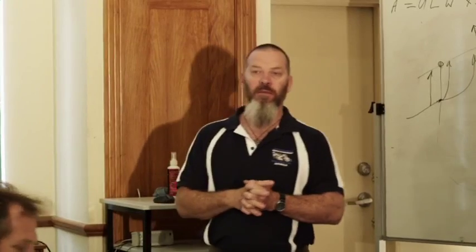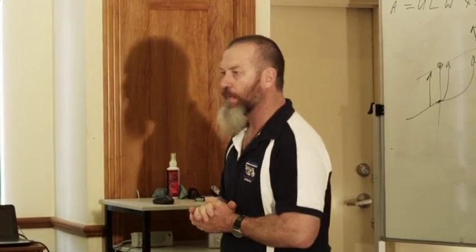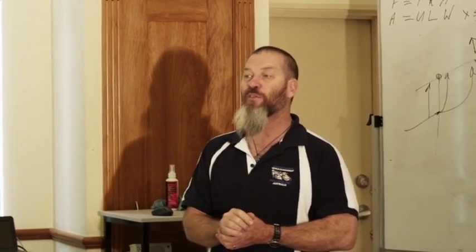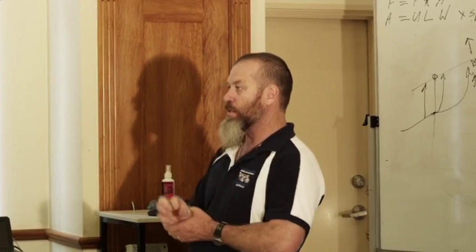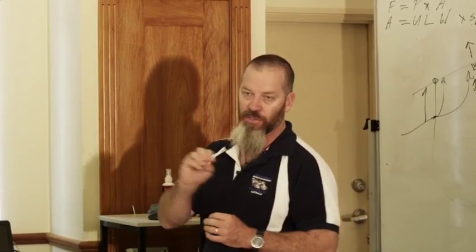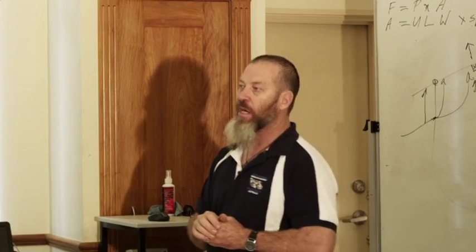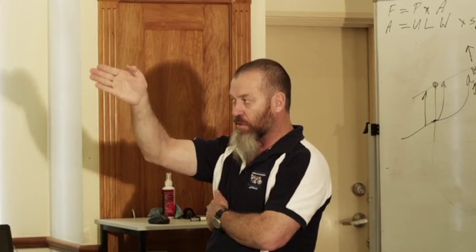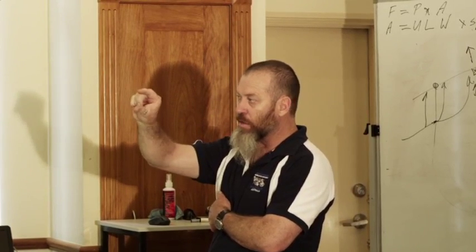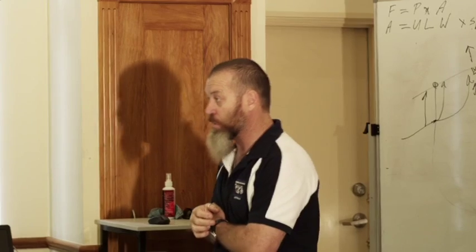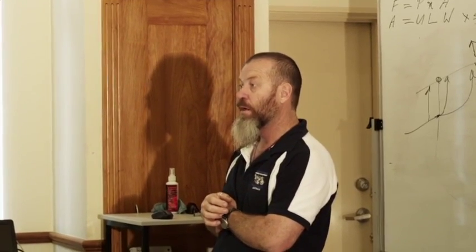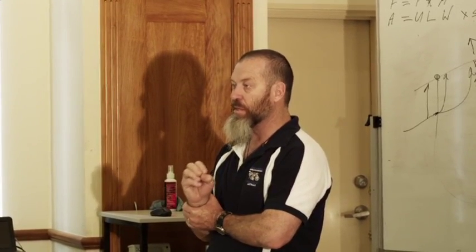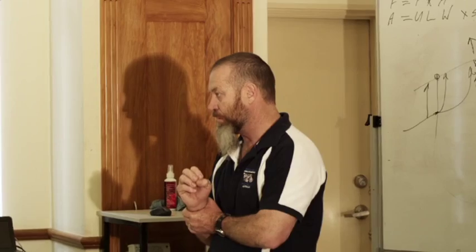Now, when you get to your span tables, and these are my rules for Task 57, what you'll find when you're member sizing your top plates, there's a little note down the bottom. When you're looking at tables, you should always be looking at the notes. And the note basically says that if you get your rafter directly over the top of the stud, you can use a minimum of the 35mm top plate. All right? Now, if you don't think that's achievable, let me tell you in Sydney now that most of the building in Sydney is governed by the project builders.